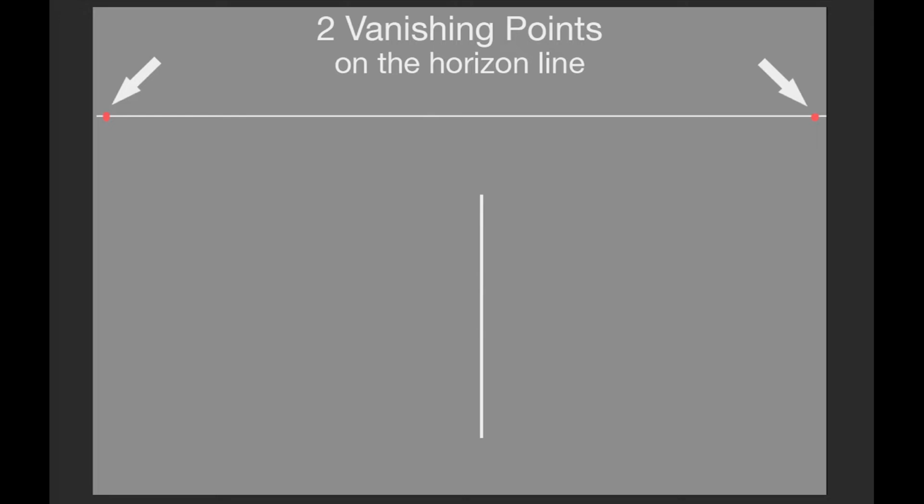The first thing you're going to do is draw a vertical line. It's really important that this line is straight vertical. There are a couple different ways you could do it. You could grab another piece of paper and lay it down on the edge of your paper to get a 90-degree angle. You could measure it with a ruler. You could use a triangle. The main thing is that these lines are going to be vertical. All of these vertical lines are basically going to be 90 degrees off your page.